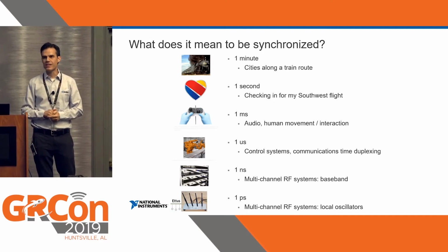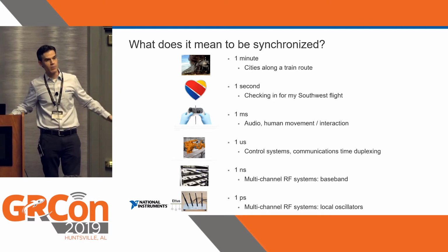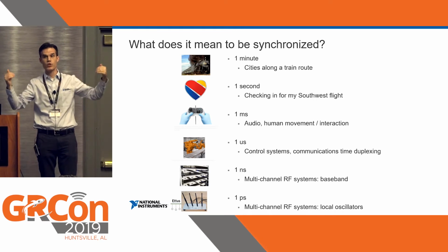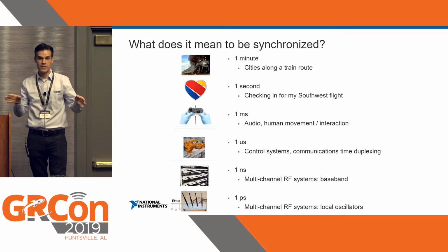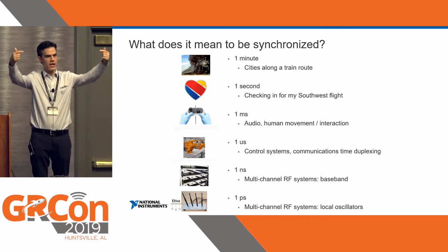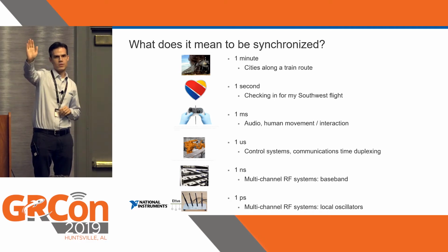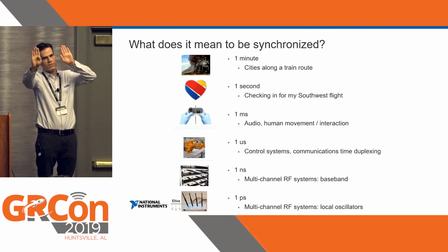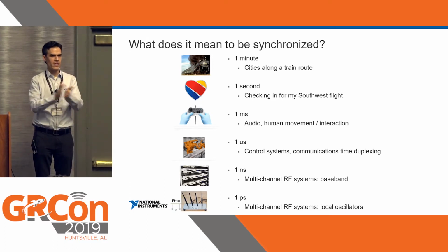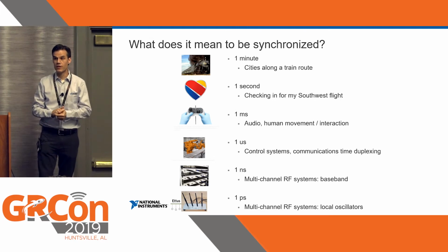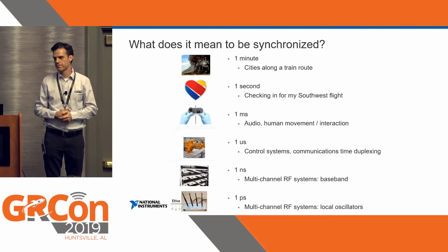A millisecond is detectable in audio. So think about it. You go to one of these huge stadium events, and they've got the big speakers in the front, right? But then as you go further back in the stadium, there's a second rank of speakers and then a third rank of speakers. And they delay the electrical signals going to the second and third ranks such that the audio coming out of the speakers in the back of the room lines up with the wavefront that was coming from the front of the stadium. And if you get that off by more than a millisecond, you'll hear the double click, the double beat of that. But if it's within a millisecond, you probably won't ever notice, right?